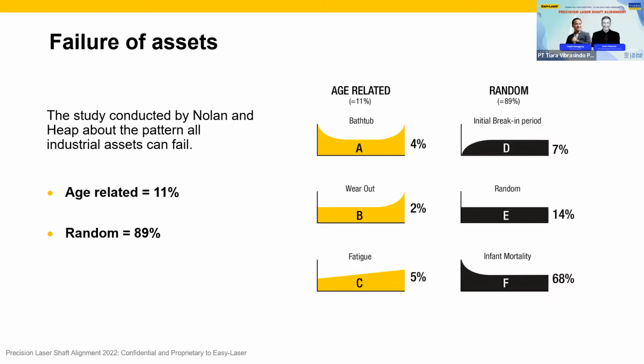It's not really possible to predict them based on some mathematical metrics or equation. And that's where we find a place for the classical condition monitoring concept: to apply monitoring technology on the machine to assess its condition, in the best case, maybe once every hour, every second for very highly critical equipment, or once a month, once per week. That depends on the equipment's criticality.